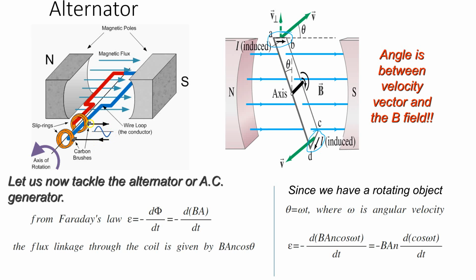and of course an overall voltage. But mind you, there's what we call a carbon brush. A carbon brush is just a piece of material made of carbon that is able to run against or touch the coil as the coil, as this ring, I should say, rotates. This type of alternator does not use a split ring. The reason we call it split ring is because you have two separate rings, but in some others you will see a complete ring that is divided, and that's for the DC generator.